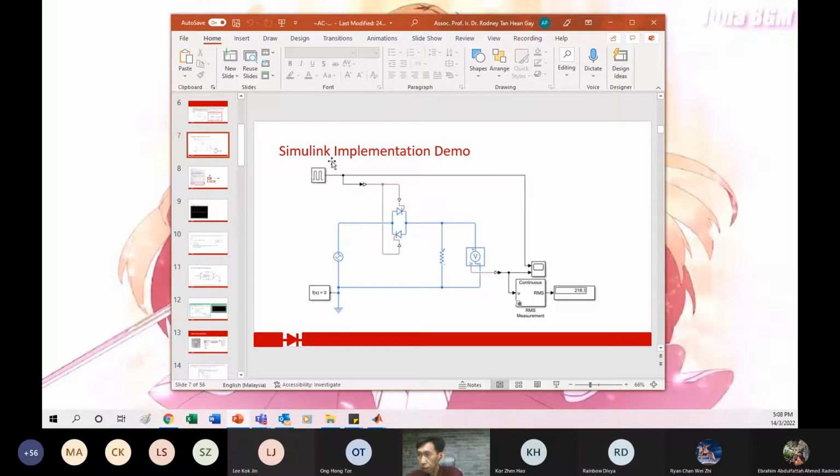This pulse generator, because we know that the supply phase starts from 0 degree, so it's pretty easy for us to actually control it. And in real AC, we may not know, the phase is not necessarily start from 0. It starts from the moment you connect to it. So how do we solve this problem?